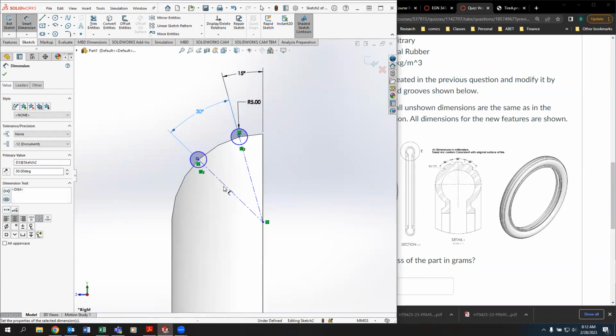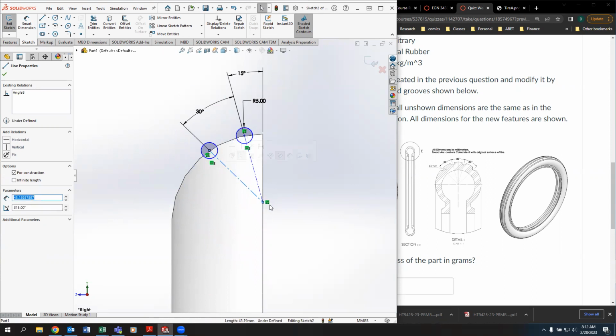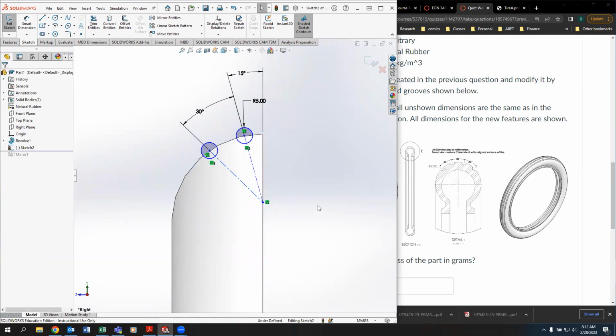So I'm just going to move this around and see what I'm missing. I probably have a relation on here that I thought I got, but I didn't. So you can see I thought I got the center of that circle, but it didn't actually keep it. So it's still missing that. Instead, it got the coincident on this vertical line. If I click on that, you can see those 2 relations.